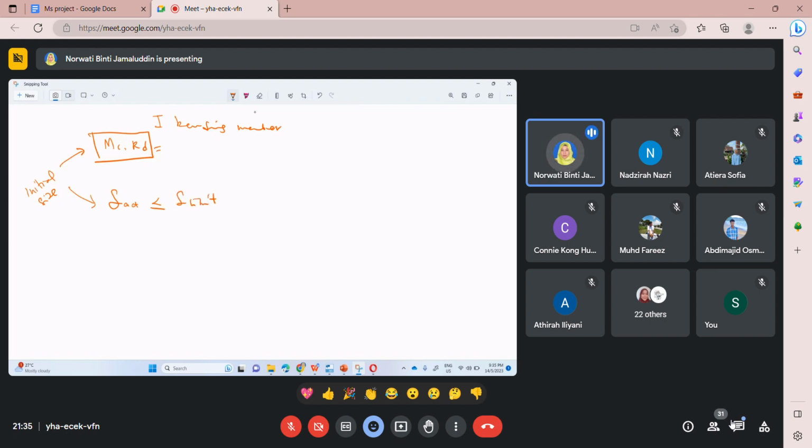Worst case scenario, it should be the same. Same thing goes here. MRd should be bigger for the safe design. MRd should be bigger than MEd. Worst case, same as the MEd.